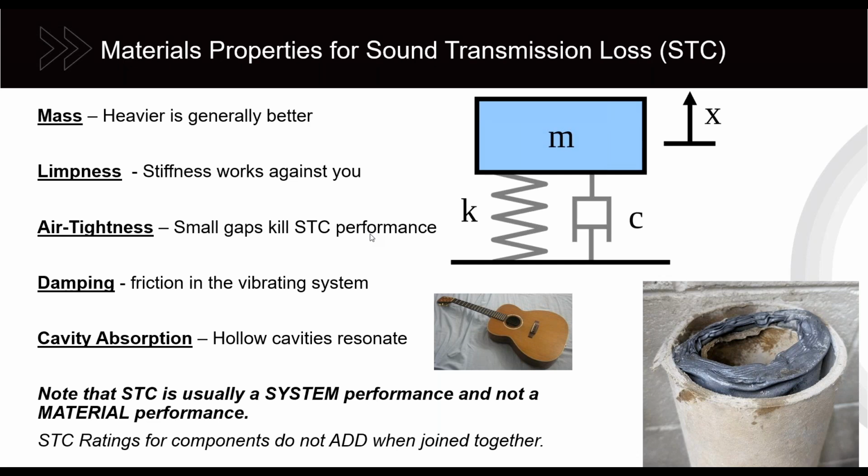If you close that window halfway, it sounds almost the same, right? 3/4, okay, now you may have noticed some change, but it's still very loud. 7/8, still very loud. It is only when the window fully seals into the top of the door, into the seal, where you get that almost airtight seal, that's when the sound sucks away and is gone, right? So you had to achieve that airtightness in the window to achieve the maximum possible STC out of that window.